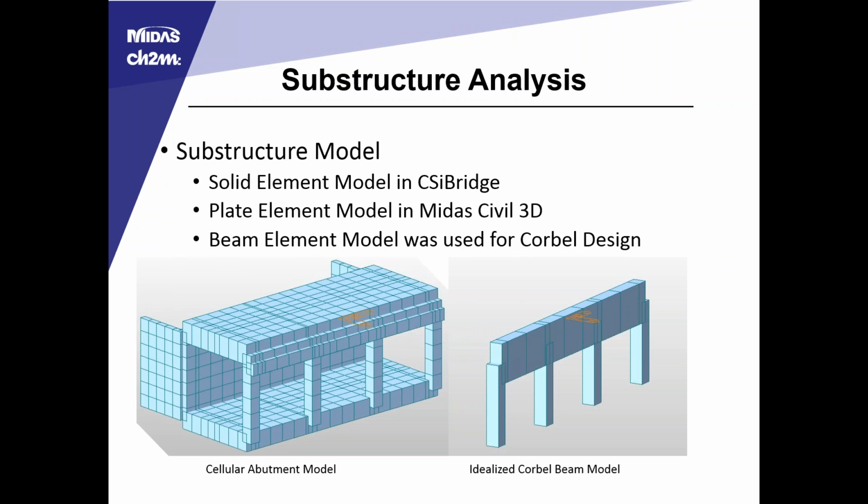For the model, it was originally modeled for primary design in CSI Bridge using solid elements, and that allows for stress interaction between the elements in multiple directions. With plates, we're a little bit more limited. With beam elements, it's even more limited.